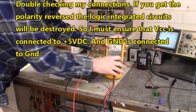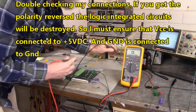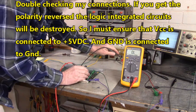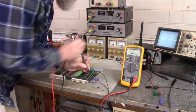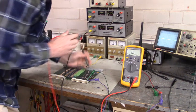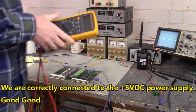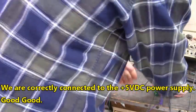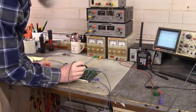Here's the double check. I want to make sure that plus 5 volts DC from that external power supply is going to VCC of the CMOS ICs on that board. And here we are checking to make sure that the ground of that 5 volt DC power supply is connected to that external power supply. And here we're good.